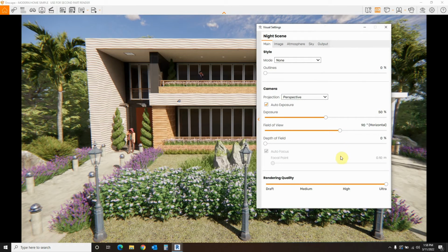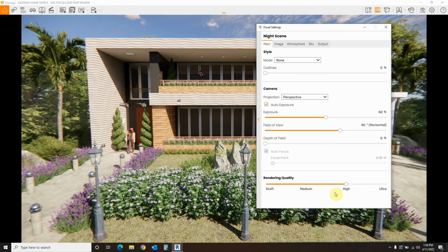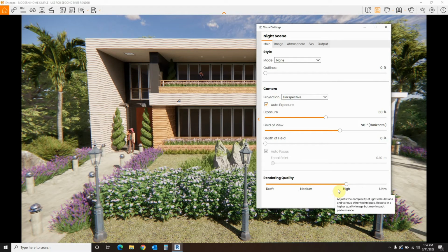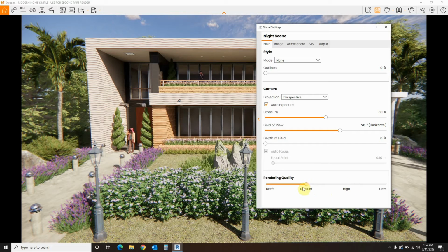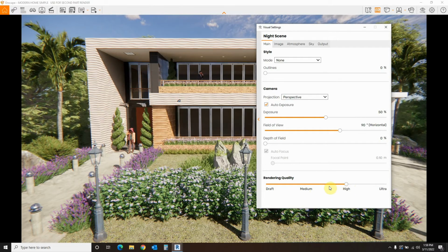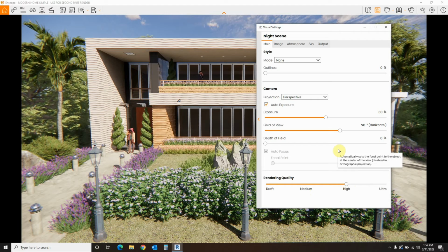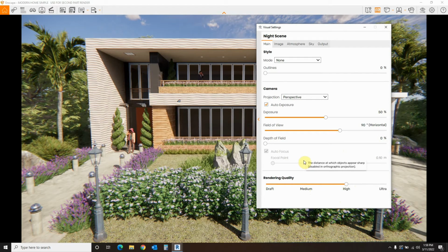Great, excellent. Here we have the ability to change the render quality, but it's the render quality for the view, because you do have an export render quality control that we'll see in a few minutes. In this case, I can actually degrade it a little bit because maybe my video card is just not strong enough to handle it. So I can move it to whatever I want to set it to. Let's go ahead and put it down to high. Ultra is a little bit too high, and high still gives me a really nice look.